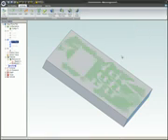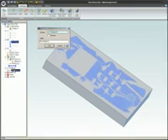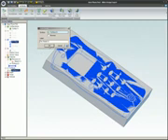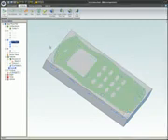The SAT part has been imported successfully and is contained inside the rectangular part. To trim away the material from the part, to create a mold cavity in the shape of the phone blank, select the Trim Model command. Select the surface, leave the Reverse box unchecked, and click on OK. The Trim Model feature has been created, but will be more clearly seen when the surface is hidden.